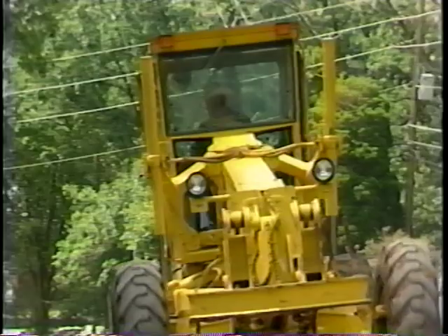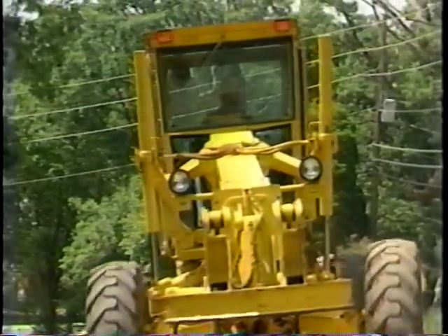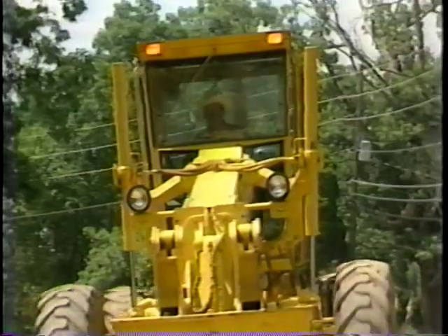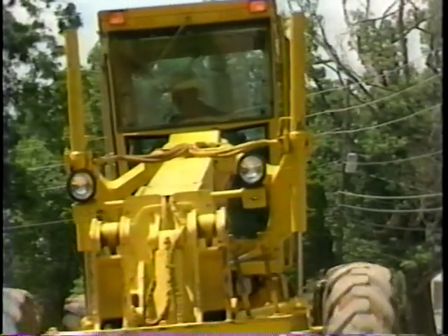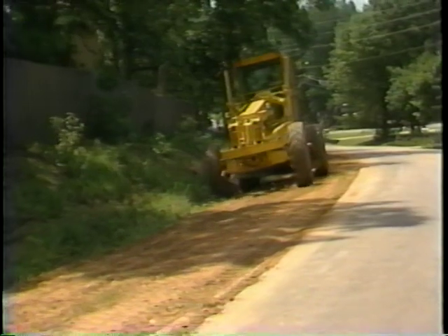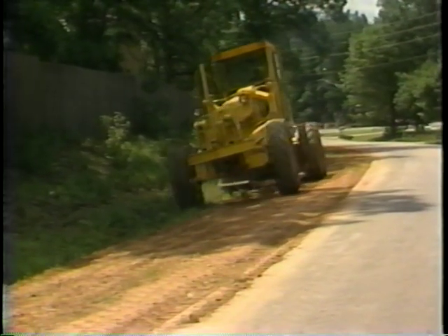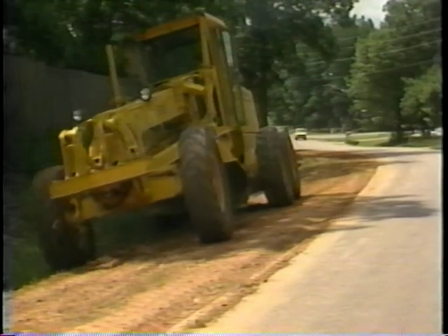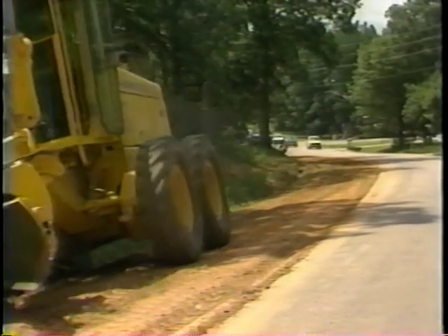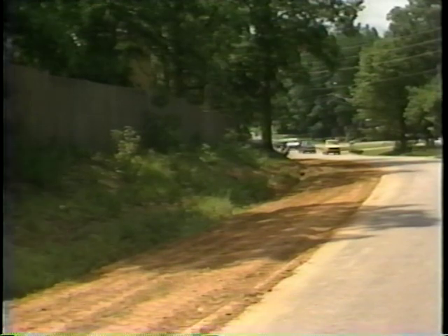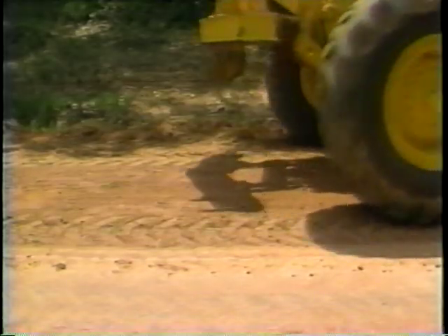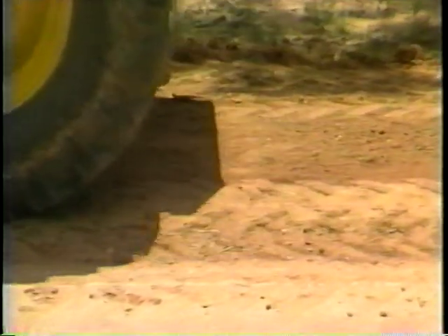Depending upon the width of the unpaved shoulder, additional passes may be needed to reshape the unpaved shoulder area. As a final step, the motor grader rides over the shoulder area to compact the material with the wheels. This reduces the potential for material being blown or washed away. In some cases, it may be necessary to seed, fertilize, and mulch the material to restore vegetation. Vegetation is desirable to stabilize the shoulder material and prevent erosion caused by water or wind.